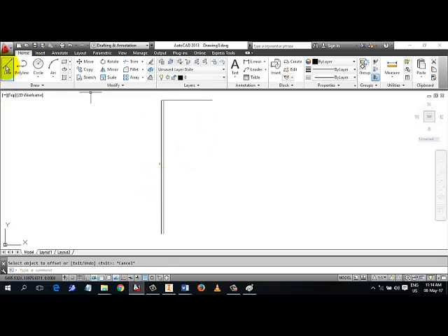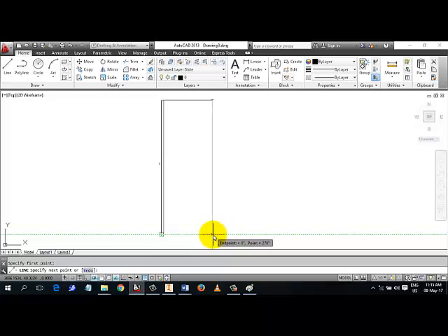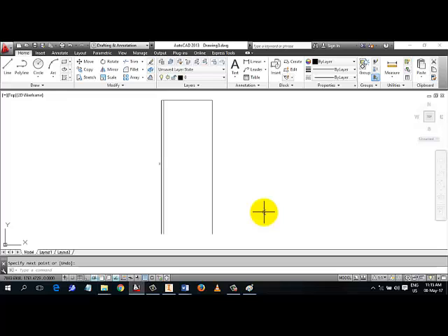But if I draw this line here and I track it with polar tracking, you see the intersection, you click there. Then I will offset that one too. O, enter. I prefer using shortcut. O is the shortcut for offset. So the same distance. I have 150 in angular bracket. I don't need to type it. I will just press enter. Then click on this and offset inward.